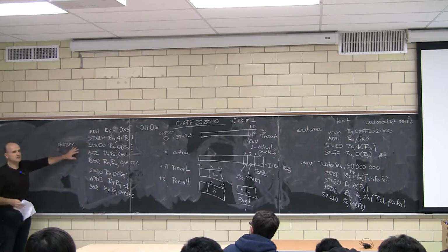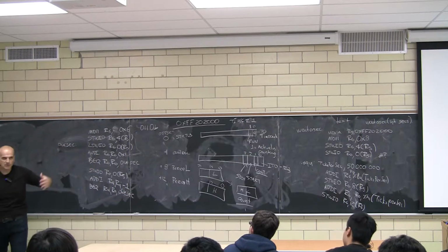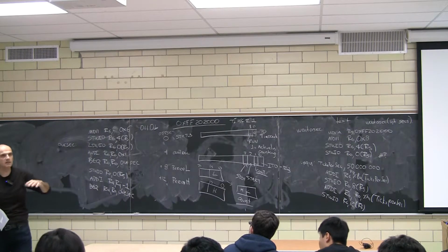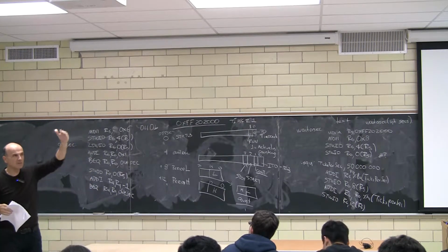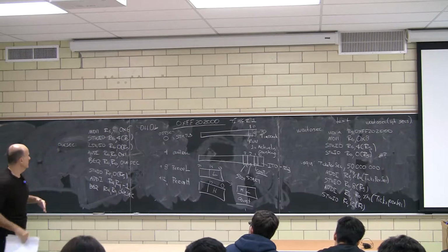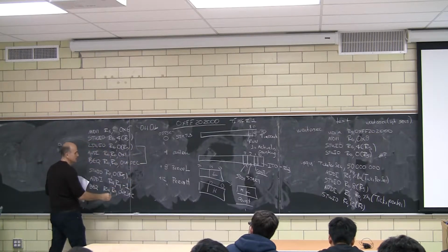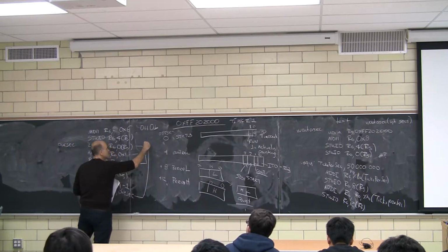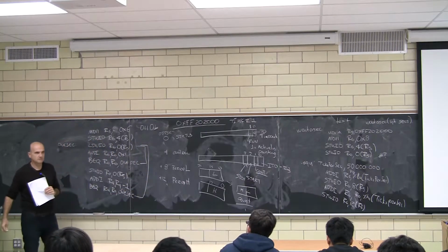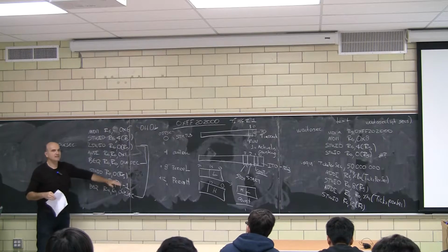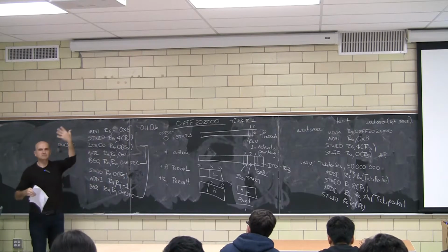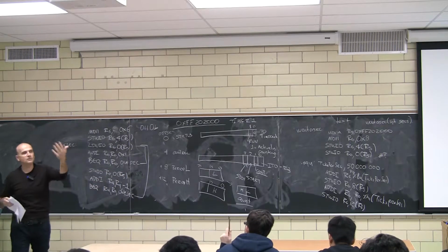So we go back to this. Remember, the counter counts continuously. The moment it times out for 1 second, it reloads the 50 million and counts down again. So this is the inner loop. This waits for 1 second. The outer loop waits for as many seconds as we ask the function to wait for. Every time we find a timeout, we reset it, and that means we saw 1 more second, 1 more second, 1 more second.